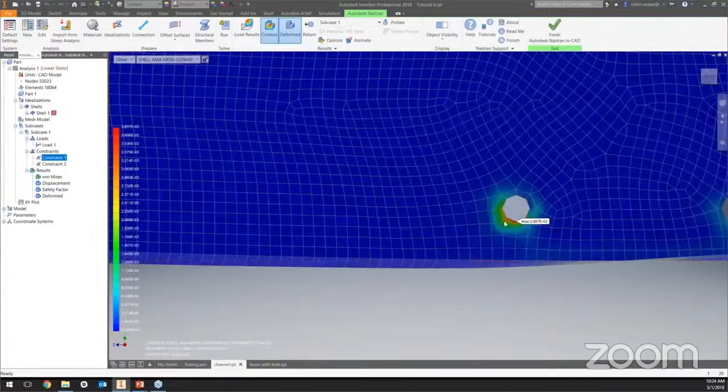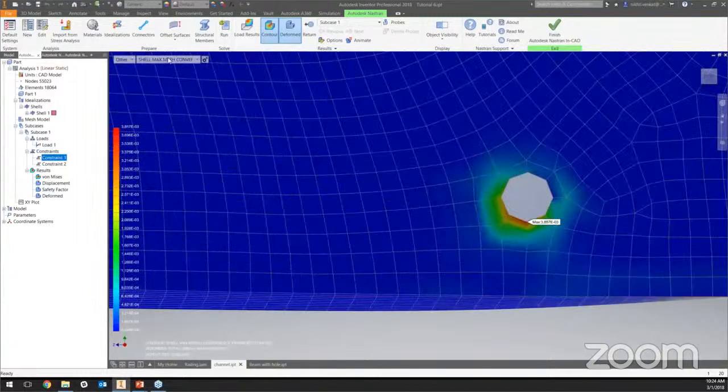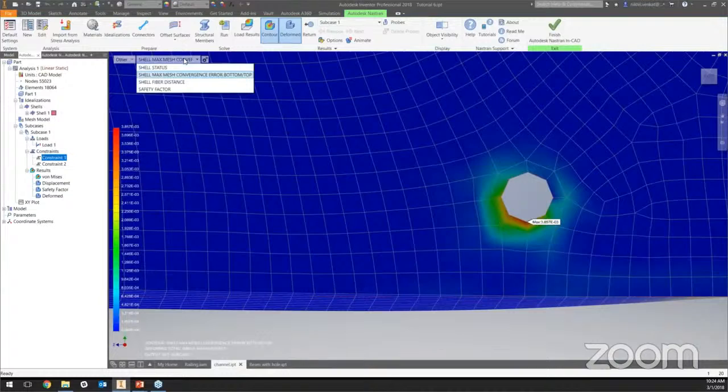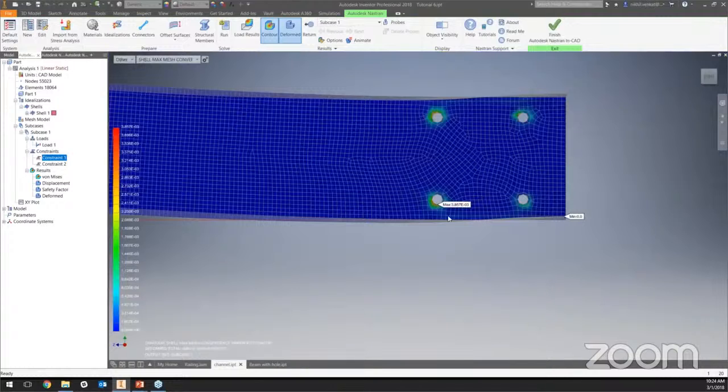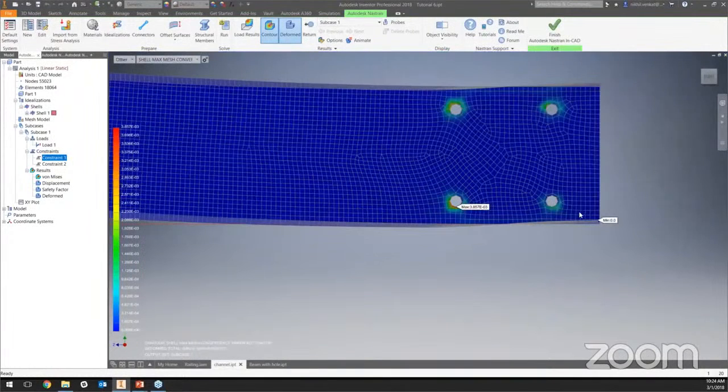Now, we know this is a good mesh because if you look at the mesh convergence error, the maximum error here is about 0.4%. So that's okay for a solution error. So this is your preliminary way to verify and validate your results from a simulation: you look at the mesh and you see if there's anything you can do to actually improve upon the accuracy of those solutions.